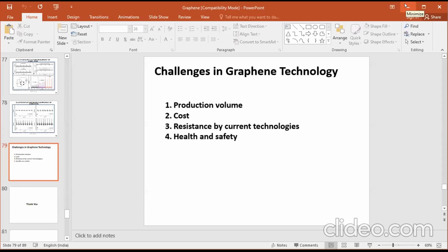But the challenge with desalination is how to make a nice membrane, because it's not easy to make a freestanding single graphene sheet as a membrane to pass water. So practical difficulties are there. Probably you may have to use some composite material in which graphene is one of the ingredients, right? Freestanding graphene will be difficult, but you have to find some support, because graphene cannot withstand the hydrostatic pressure. So it should have some support, either in the form of a composite or some other method you have to find. Other than that, theoretically it's possible. Some research is also going on in that area. You can find it elsewhere in the literature. Yeah. Thank you, sir.